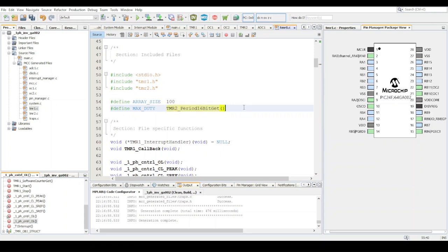As explained earlier, we're essentially using Timer 2 to generate the PWM. The output capture module is generating the PWM, but it's using Timer 2 as a base to do that. So essentially the PWM is generated using a counter system. It counts up and then goes back to 0, counts up, goes back to 0. That's actually done in Timer 2, and then the output capture module does the comparison of that. And then out of that, we're able to modify the duty cycle.